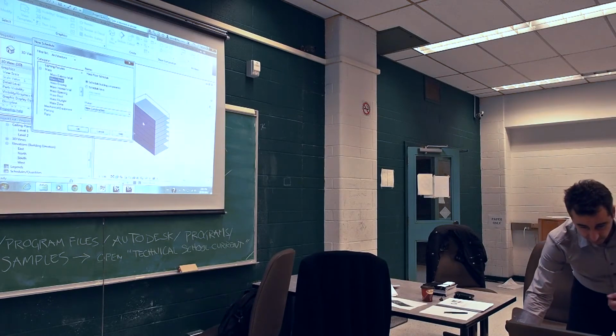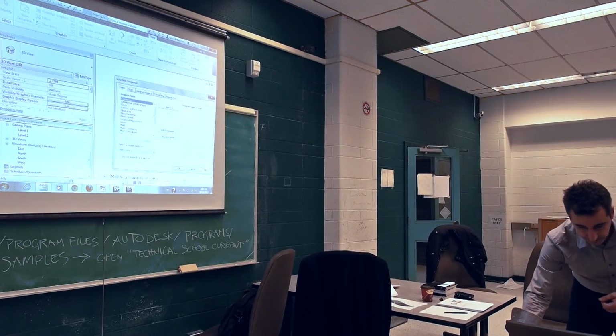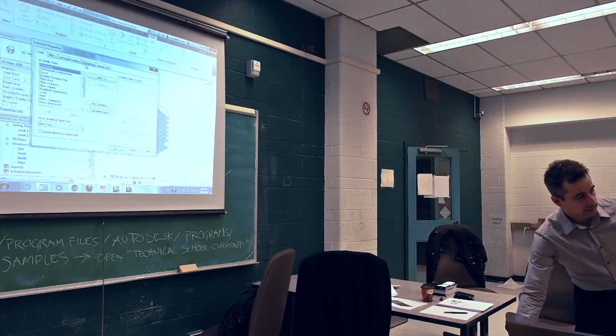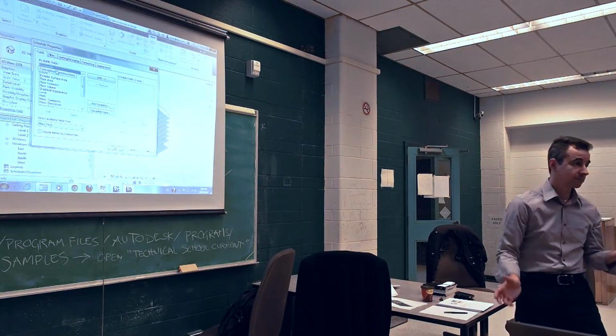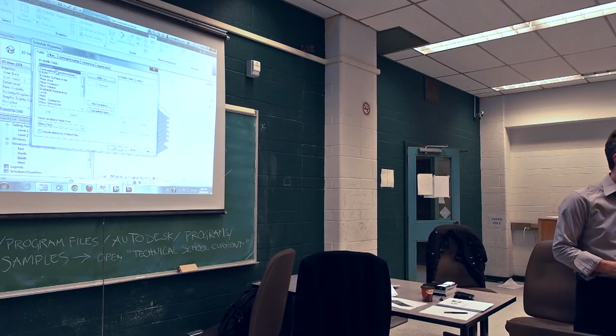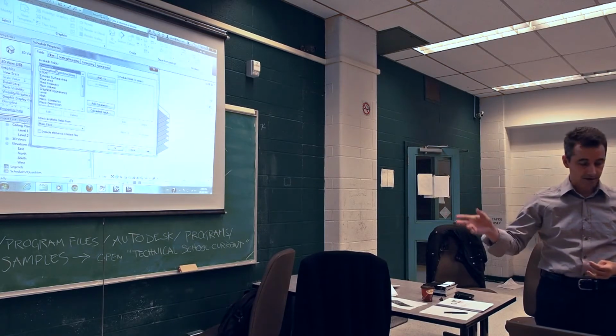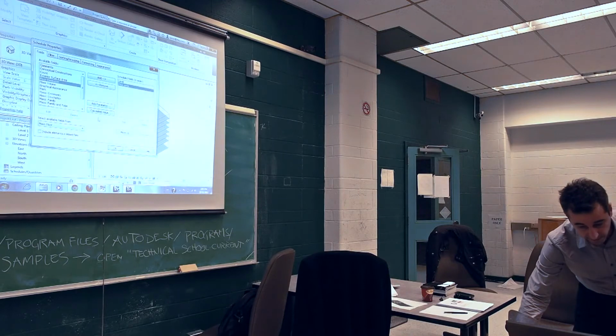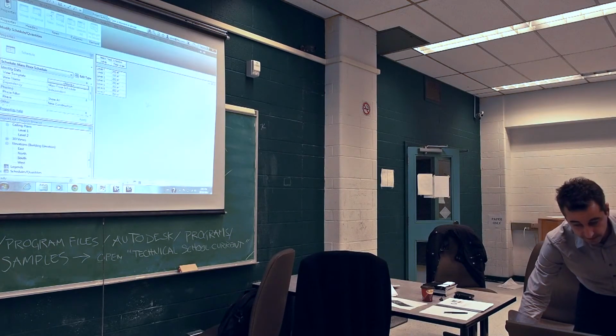And if I choose mask floors, then I'm presented with another set of options. What do I want to schedule? And everything in here, on your left-hand side, in the available fields, is, guess what, available fields to schedule. So you can schedule every single one. Really, at this point, I want the level and I want the floor area. And that's all I want. This is my schedule.